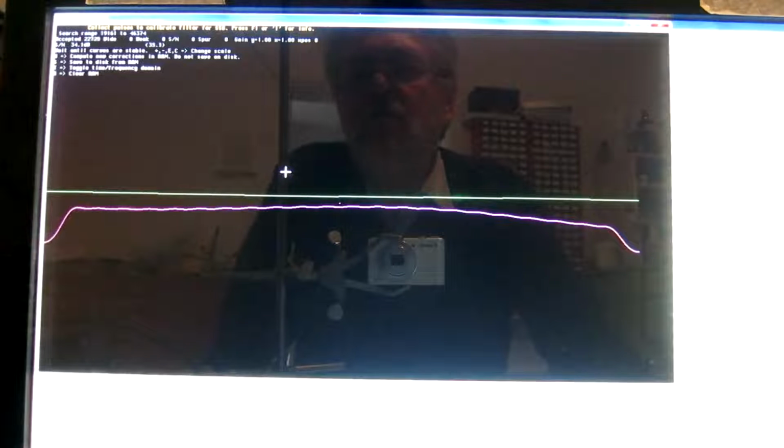The magenta is the power, and the green is the second derivative of the phase. And it is power and phase as they come from the Fourier transform. The reason that it is the second derivative of the phase is that the phase itself varies from pulse to pulse and cannot be averaged. The first derivative is also varying, but the second derivative, that is always the same for all pulses, so it is possible to take the average of that.